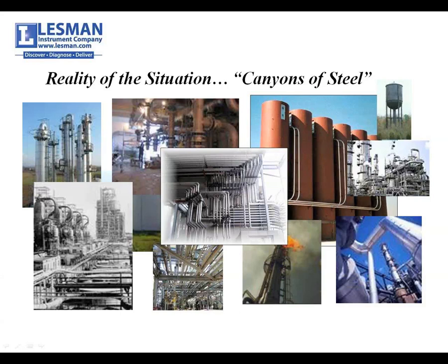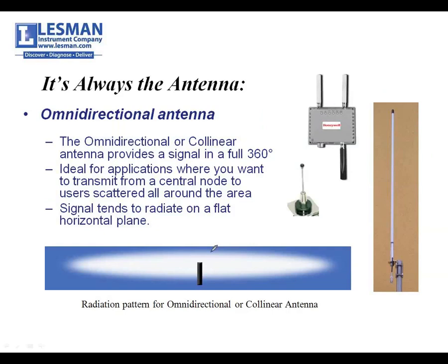Another general rule of thumb, if you can see a path for a man to walk down or a car or a cart to drive down, the radio will fire right down it very nicely. Radio will work in a tunnel wonderfully as long as you don't go around a corner. If you need to go around a corner, that's when we start talking about a strategy where we include a repeater radio, which does nothing more than catch and resend at full power whatever it sees. Okay?